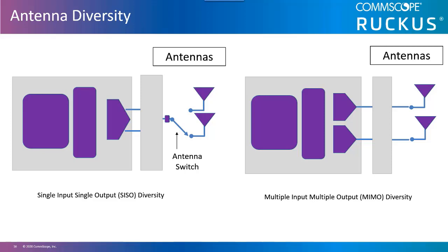They use only one antenna at a time and change antennas only when a received signal is weak or has a poor signal-to-noise ratio. Simple diversity and multiple signal combining techniques can be effective even if only used on one side of a link. Diversity antenna systems are used to improve transmission and should never be used to provide coverage in different directions. SISO diversity was used commonly on systems supporting legacy 802.11a, b, and g transmissions.